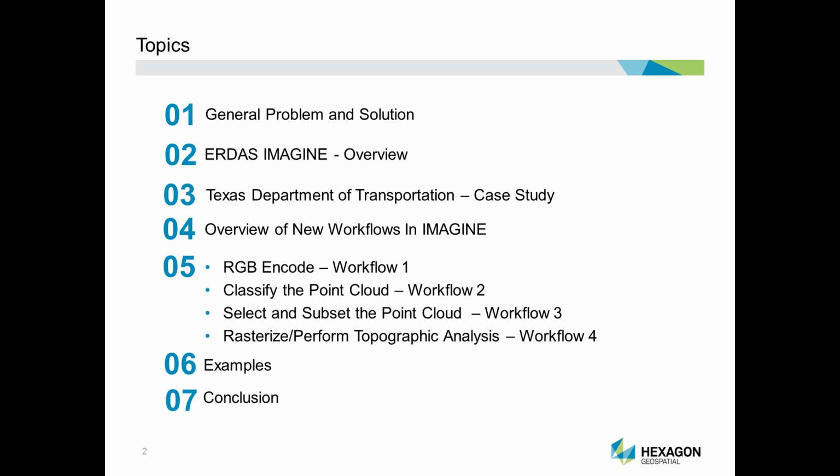And these are the four workflows that I focus in on here. The RGB encode, workflow number 1. The classify the point cloud, workflow number 2. Selecting and subsetting the point cloud, workflow number 3. And then rasterizing to perform topographic analysis on that point cloud as workflow number 4.